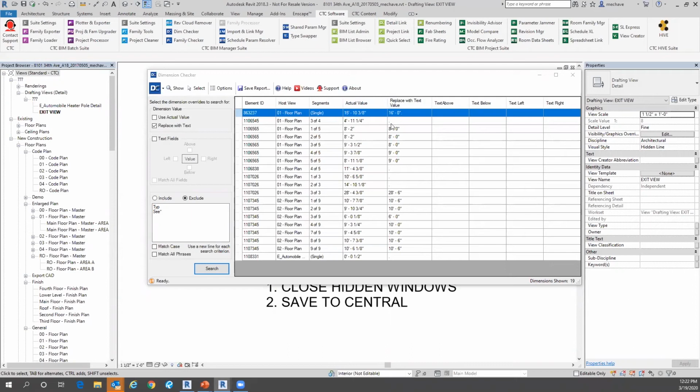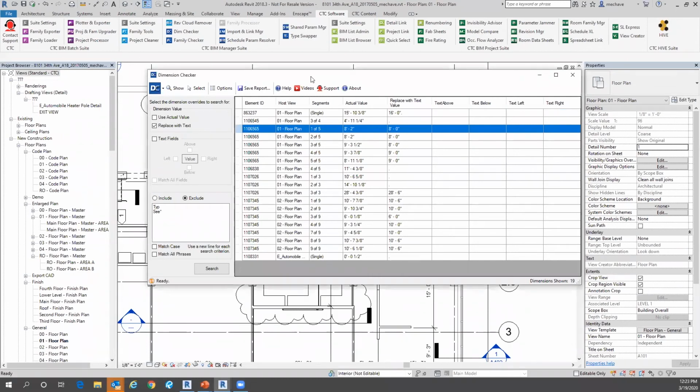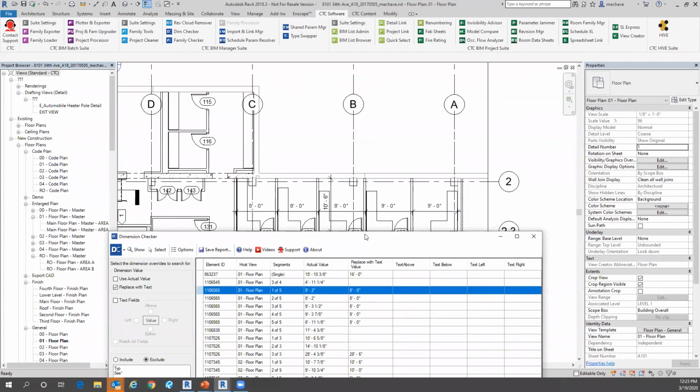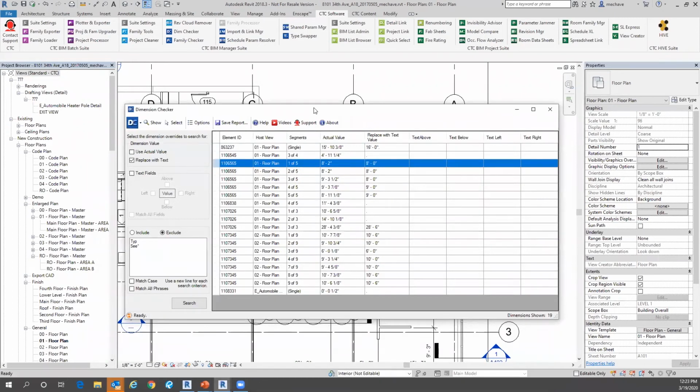And this text was actually placed with a period, and they probably put text over it as well. And let's say I wanted to see these instances that have been replaced with text. I can actually double click on it, and it's going to bring me to where it is in my project. So in these instances here, all of these 8-foot items, all the way to 9 foot over in these room dimensions here, I can see that there's actually a string issue here, and somebody's been replacing them with text items here. So as you go through here, you can see what instances have been replaced, and you can address it from this location.